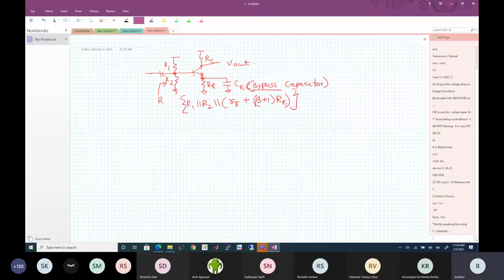So it will see this and think, this is nice, I have a path, I don't have to really work hard. I'll go directly here because the electron has to go home to the ground. It cannot stay anywhere else. It has to rush to its home. So it will try to find the quickest way it can reach, and it sees this capacitor is there, so it will go here. As far as the AC signal is concerned, the variation will go through the capacitor, but the DC will certainly go through this resistor, and therefore the AC signal is bypassed to the ground. So this is called a bypass capacitor.